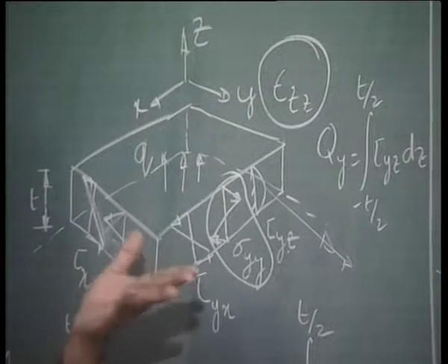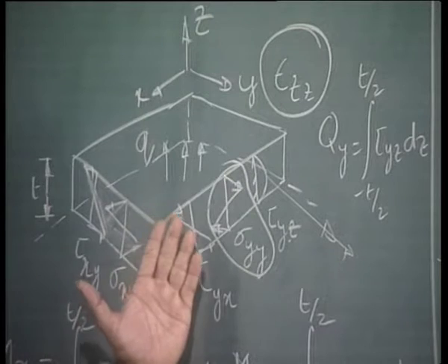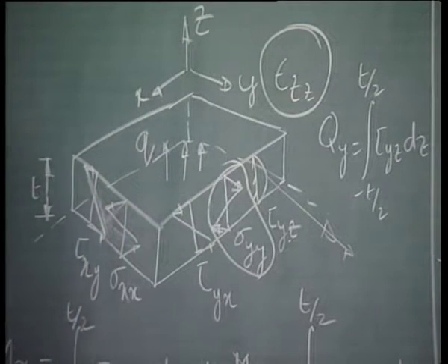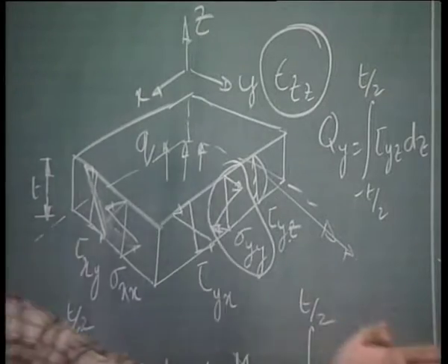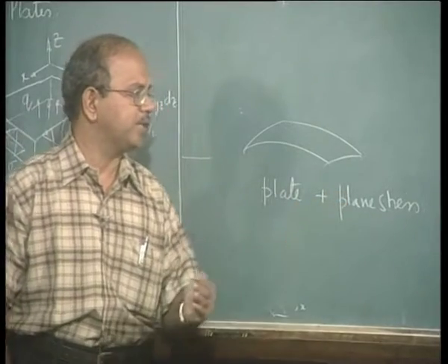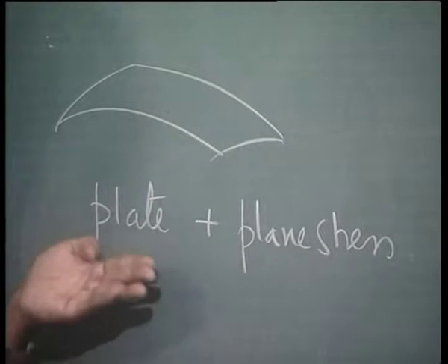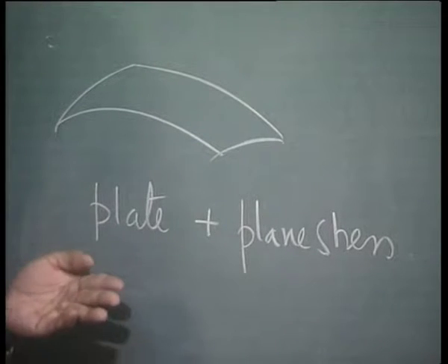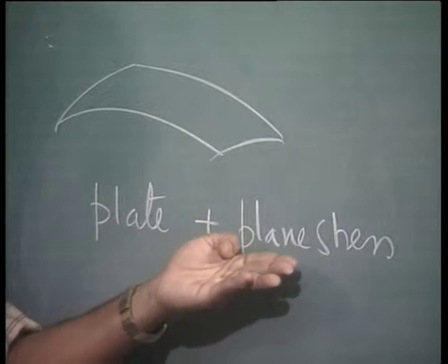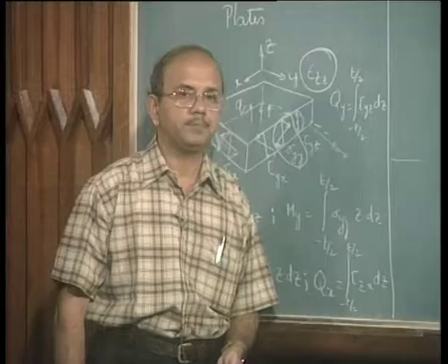They do not have a separate plate element. They use shell elements to model plates, because, as I told you just now, since shells combine plate and plane stress behavior, we can use the plate behavior alone to model the plate, and the same elements can be used for plane stress as well.